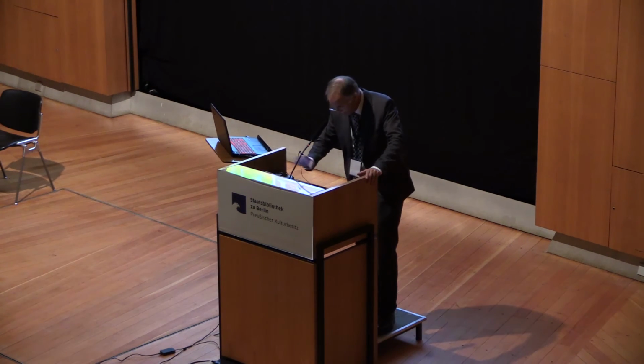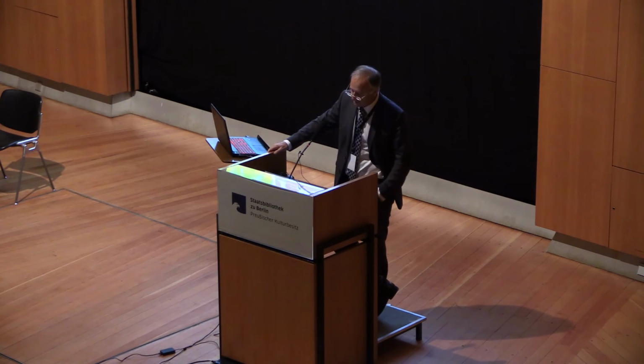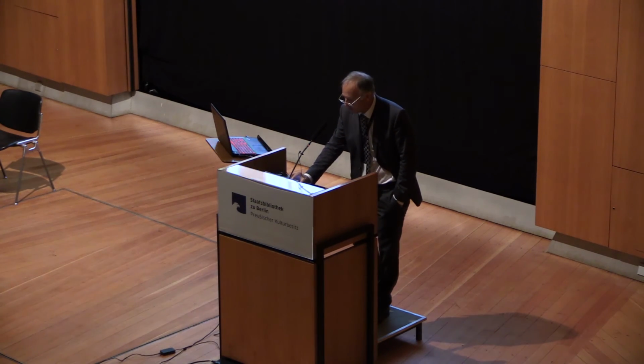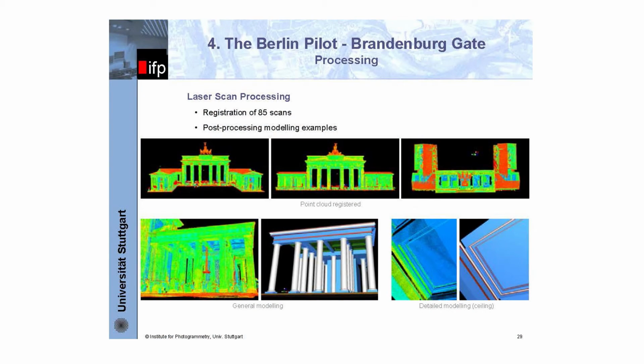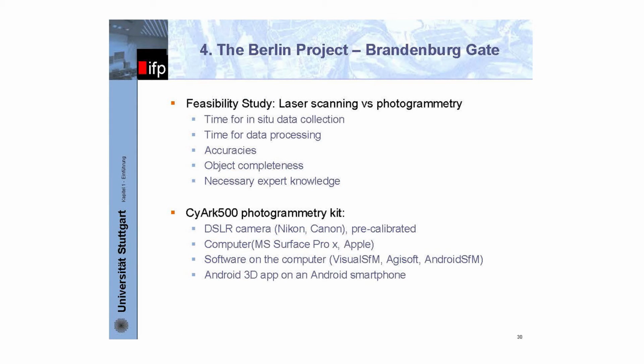In the meantime, we registered all the 85 laser scans, and now we are processing the point cloud just to come out with a CAD model you see over here, but this will take a while. Finally, we'll come out with this feasibility study. Here we are looking at the time for the in situ data collection, the time for the data processing, comparing accuracies, the object completeness, and also what about the necessary expert knowledge.